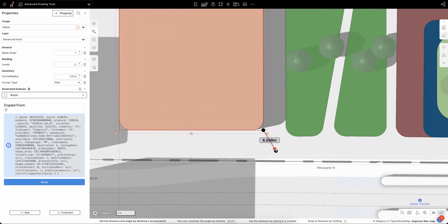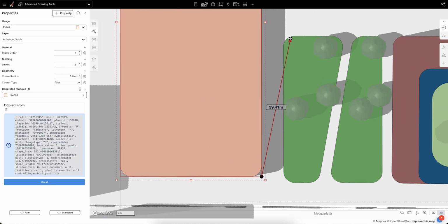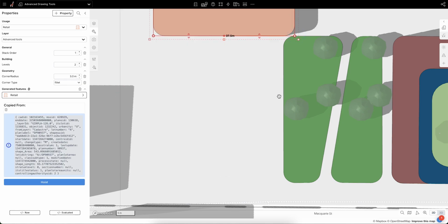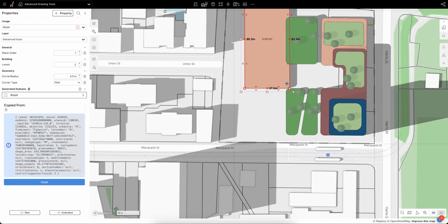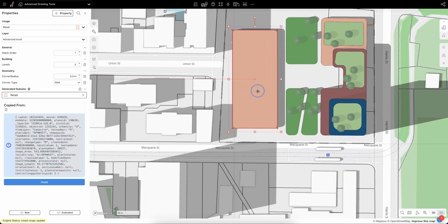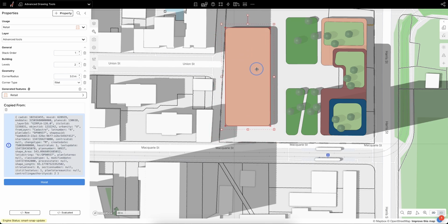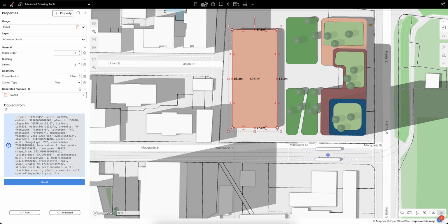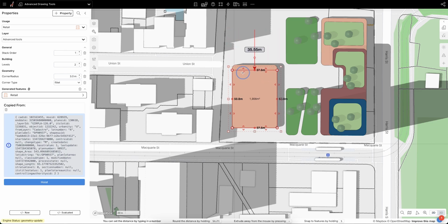So if we wanted to move this for some reason up aligned to the start of this landscape, we can click that destination, and that way we control the move through those 2 points. So rather than your typical method of moving geometry around, the drag and drop method, we do have that more controlled version of moving around that geometry.